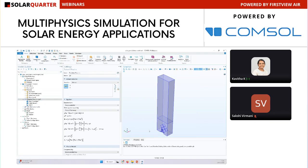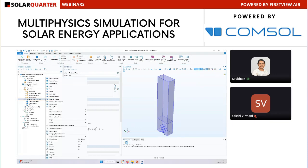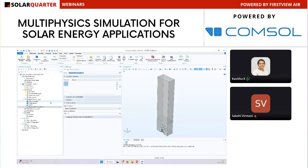Since we are modeling a periodic problem, we need to have the periodic flow condition. So let me apply a periodic flow boundary condition. Here the periodic flow is going to be in the XZ plane. This node will specify the pressure difference in the streamwise direction, which is the XZ plane here.